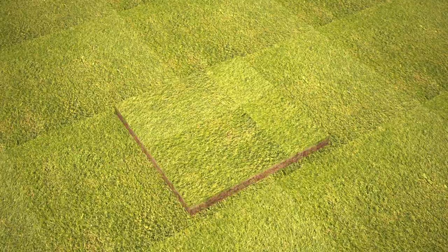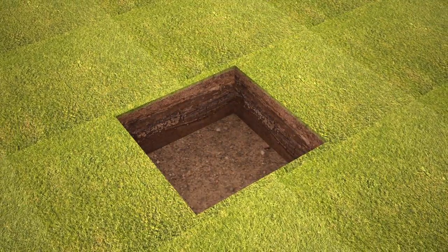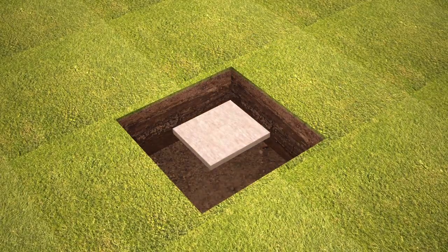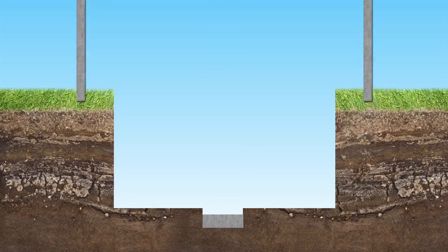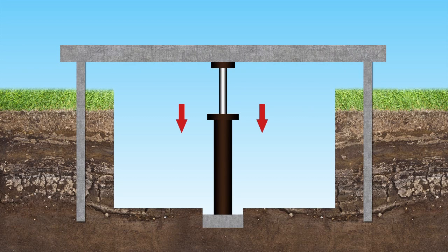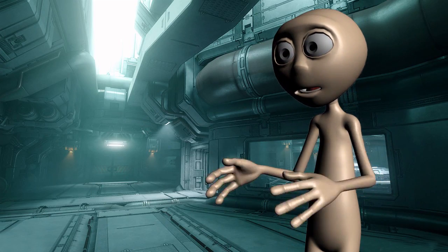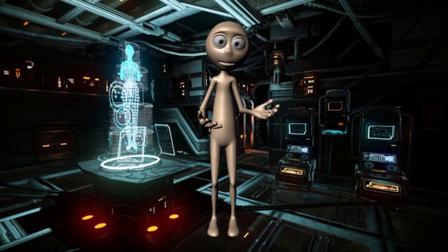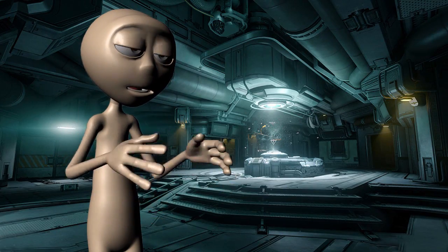Well, the ultimate load of the plate is indicated by the break in the graph between load and settlement. The advantage is that it can be used to determine the settlement of the foundation for the same load intensity. In some situations, when the quality of the undisturbed sample is unacceptable, in those cases, the plate load test can be used. And Chatur has something to say about this. He has the disadvantages for the same. Well, the disadvantages can be the time taken for this test and the procedure of digging up to the depth.